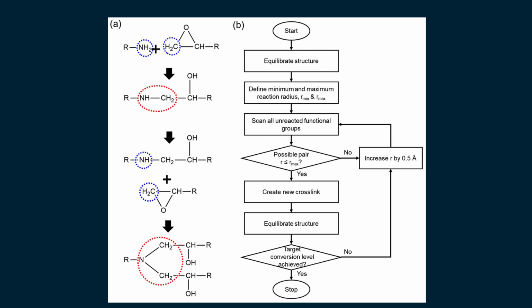Due to its low reactivity, DDS is often used with slight excess concentrations or with accelerators such as boron trifluoride monoethylamine, BF3-MEA. Cure schedules typically involve prolonged heating at high temperatures to achieve optimal properties.